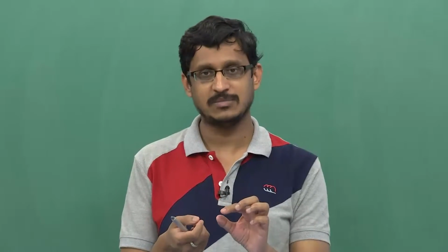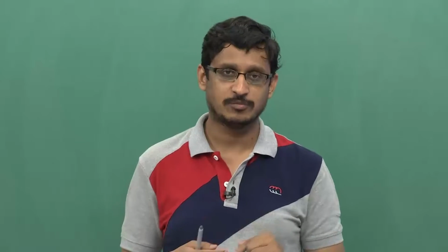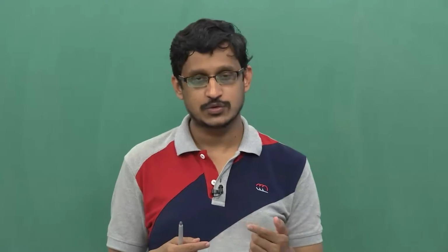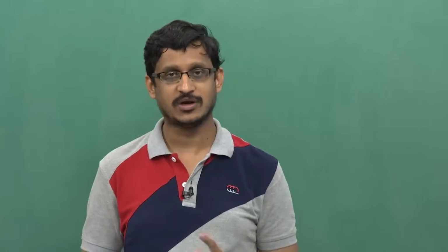In between, you might also have to do something called splicing. Splicing means that you are taking two optical fibers, but you are not putting them through a connector, but rather fusing their cores together. This process is a low loss process, and it is used to couple many other components along the way. So, the point here is that you start with the transmitter, then as you go up to the receiver, you will encounter various components, and each of those components is going to give you loss. After you calculate the total loss, whatever power you receive at the receiver will be the power that you have to use in order to recover the data.